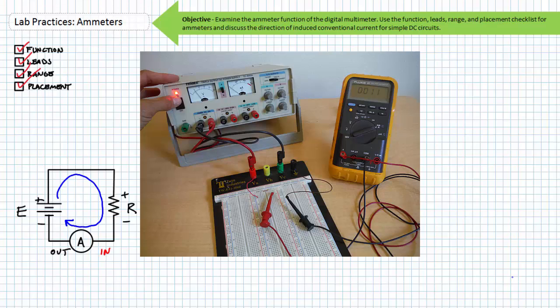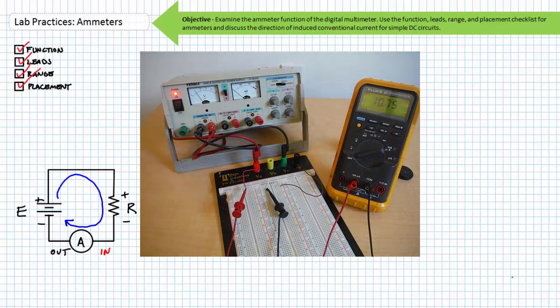What about the alternate input for the milliampere/microampere mode? Notice our observed value of 11 milliamperes isn't especially accurate, nor is it especially detailed. We know 11 milliamperes is close to our expected value of 10.6 milliamperes, and that current is traveling in the right direction. However, if we want a little more accuracy, we need to step down to the milliampere input while still in the milliampere/ampere mode. In this case, it shows we're actually observing 10.75 milliamperes of current.